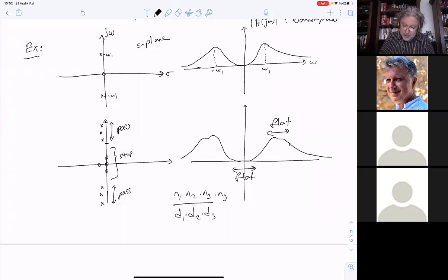However, on the contrary, if your denominator amount is more, that is, if you have more poles, then the denominator will go to infinity, which will make h of j omega shrink down to 0. Okay, they will go down to 0 as omega goes to infinity, which is a desirable property.